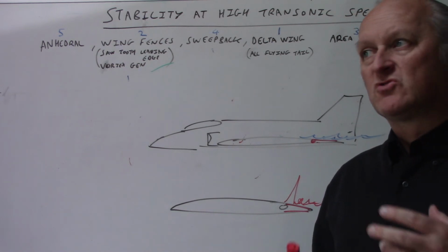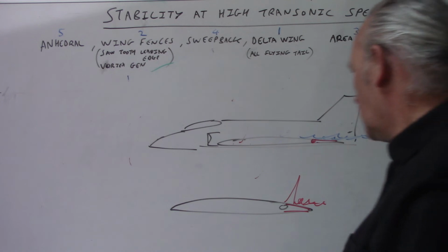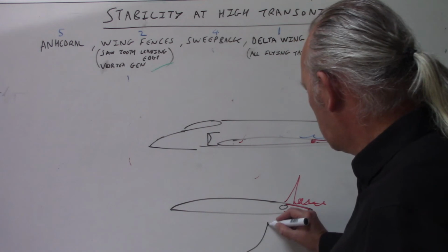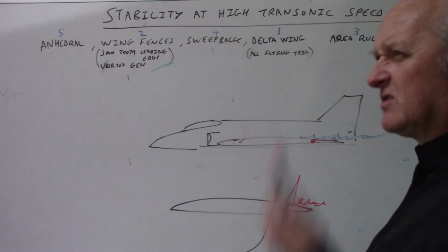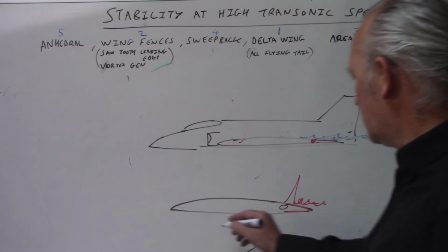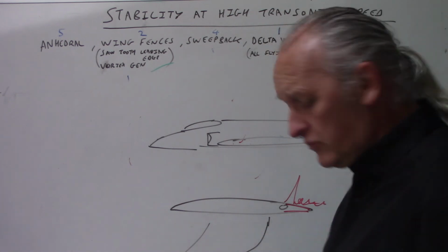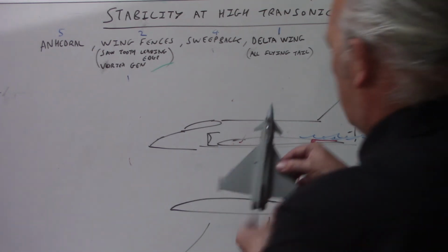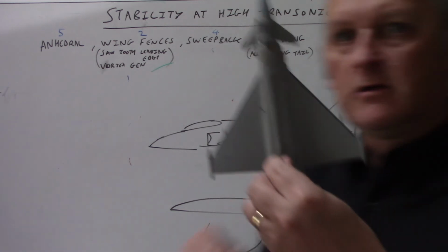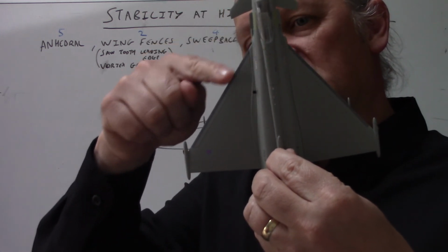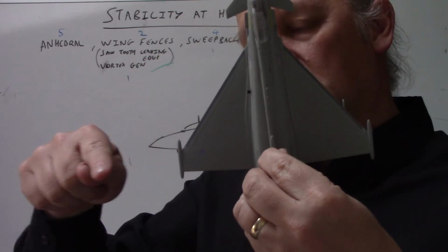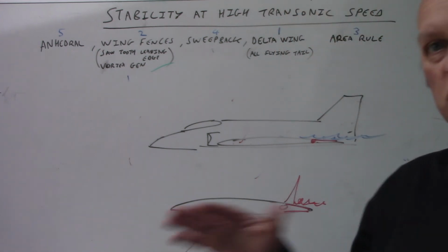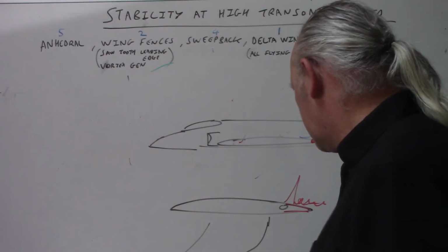Okay, so there's various ways around that. Concorde, for example, has a crescent wing, which is kind of like that sort of shape. No, sorry, it's not. Sorry, canted delta, not crescent wing. Crescent wing is that sort of shape. So the Typhoon, if you look along the wing from there, that looks like a straight delta. If you look very closely at a real one, you'll see that it actually is a slight crescent shape, and it changes towards the edge of the wing. There's various reasons for that. It gives it more lift at low speed, and there's all sorts of stuff like that. Forget crescent wings for now.